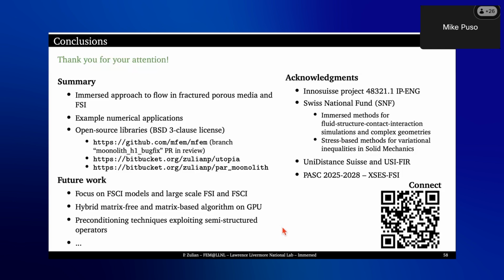Yes, so there is actually a paper where they show for this type of approach that there is a mesh ratio that needs to be respected. Typically, let's say, in our case, the mesh of the fluid needs to be the same or finer than the mesh of the solid. Otherwise, you will have all sorts of instabilities and bad effects. The only problem, if you have a fine fluid mesh in our monolithic approach, is that the method becomes much more expensive because of the Schur complement that you compute. But typically, for the immersed domain, the fluid mesh needs to be much finer or the same as the solid mesh. Otherwise, it doesn't work.